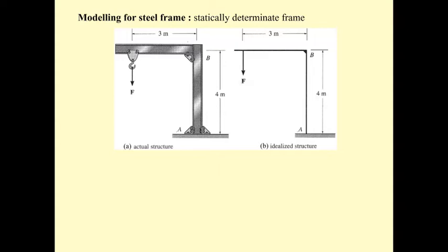that can be hinge, that can be pin, that can be fixed. The roller only has one reaction force. The pin has two reaction forces because the pin prevents horizontal and vertical movement. The fixed has two reaction forces and one reaction moment because the fixed won't allow horizontal and vertical movement and also won't allow the rotation.